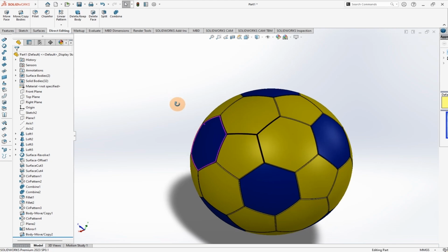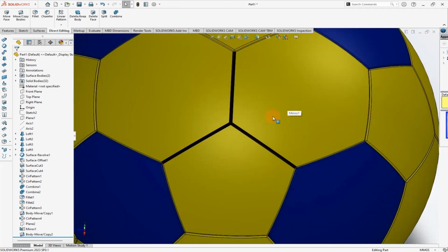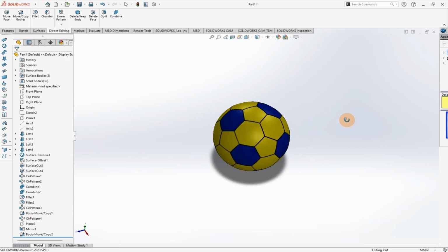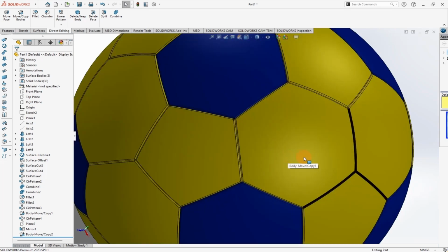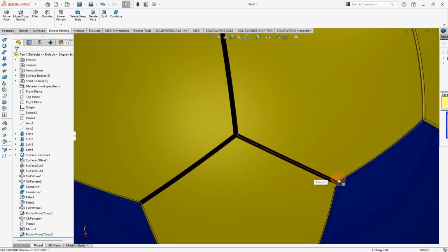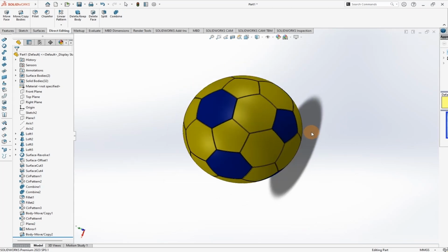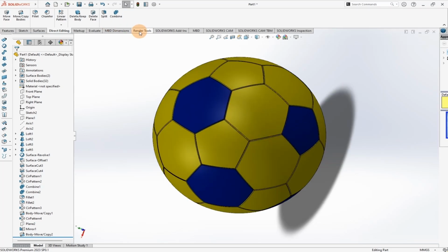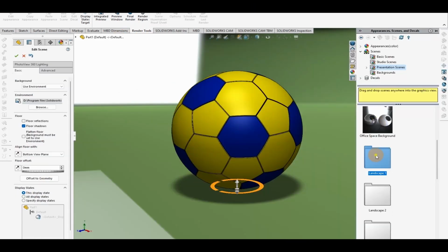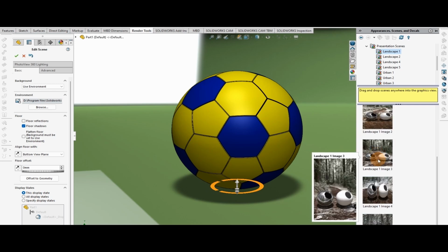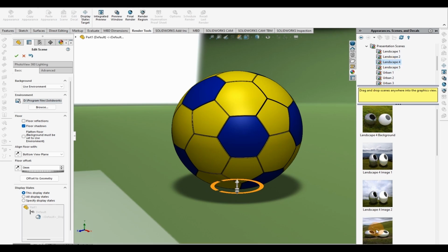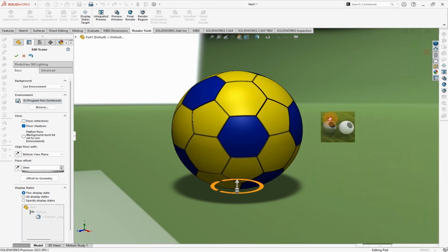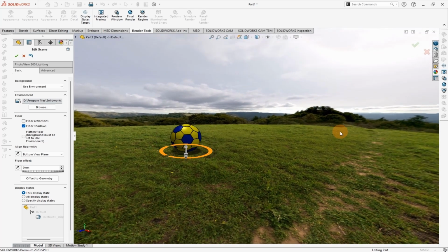what remains is we want now go to render environment. Under render environment, you can see you can also apply appearance on those boundaries where we added fillet. So go to render tool. Under render tool now we can scroll down to the appropriate environment you like. I like this one. Once you select the one you like, just click on the perspective view.